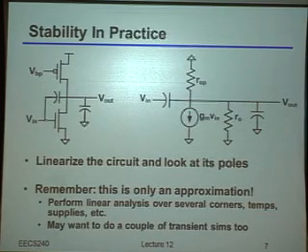Okay, so now the question, of course, is, what do we do in practice? I don't know too many people who like to do nonlinear time-varying math. At least I certainly generally don't. So what you typically do is you say, well, fine, the circuit really is nonlinear and time varying, but I can usually linearize the circuit given some operating condition. And then I can do all of these procedures that we talked about before, right? So I can look at the poles, I can get the phase margin, I can get the gain margin, and so on and so forth. Okay? So indeed, that is still what we're going to do. But we have to remember that this is really only an approximation.